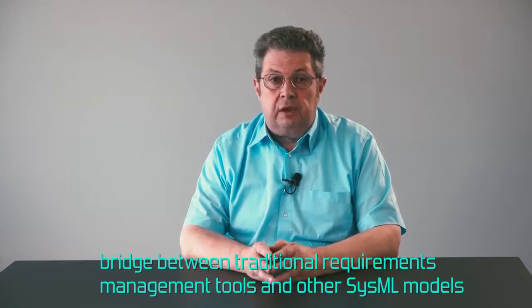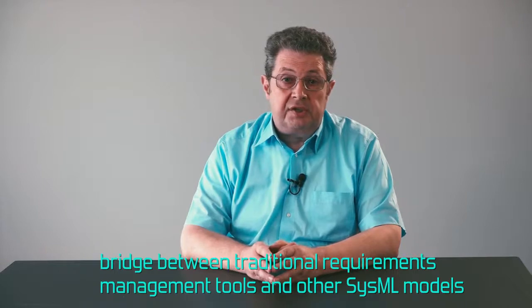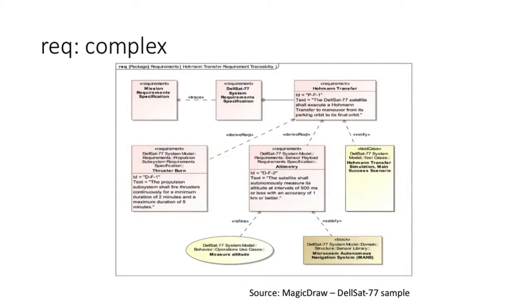The requirements are modeled by a requirements diagram, which is totally new to SysML. It provides modeling constructs that help represent text-based requirements and relates them to other modeling elements of any kind. They are intended to provide a bridge between traditional requirements management tools and other SysML models. These diagrams display requirements, packages, other classifiers, test cases, rationales, and relationships.